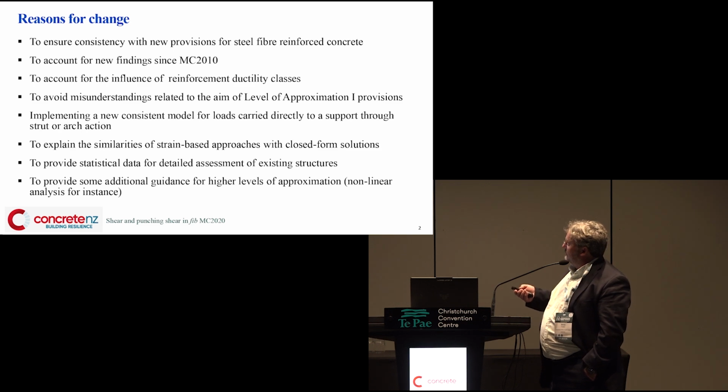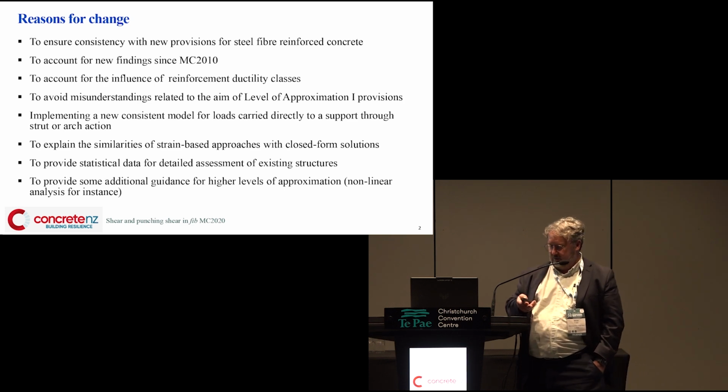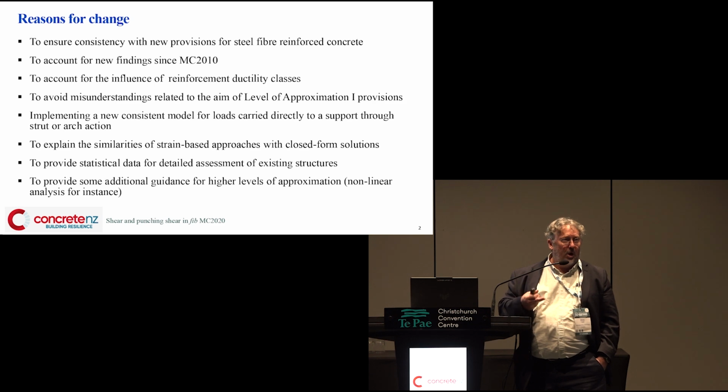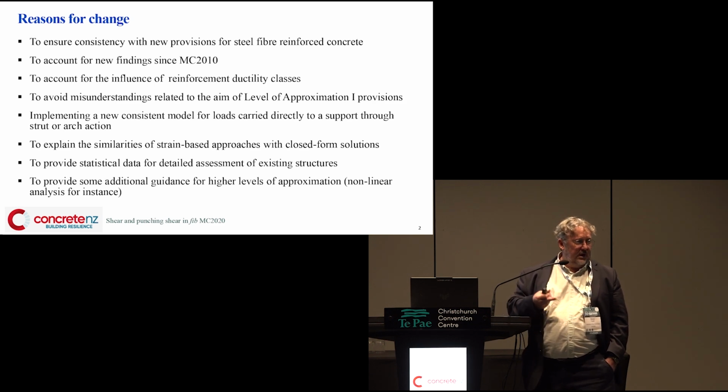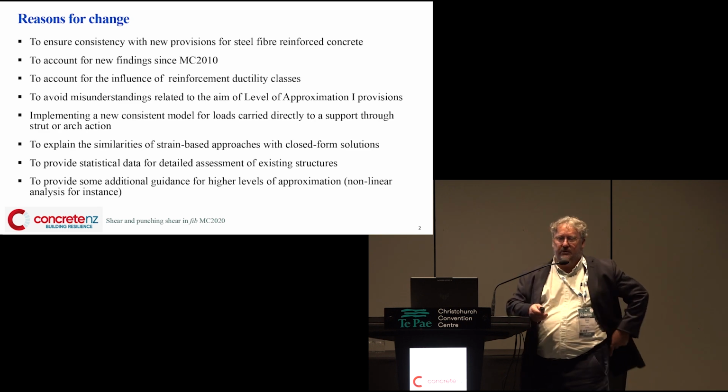And then look for a more consistent way of modelling those direct supports. Some people like the strain-based, some people like closed form solutions, but they come from the same theory and model. And again, this comes down to how you work in consensus forums. Then to look at the statistical data for assessment of existing structures. There's quite a lot in there. I won't go into that in great depth, but assessment of existing structures, particularly non-compliant detailing, is in the code, so it talks about how you deal with those, and then look for higher guidance on nonlinear analysis and the like.